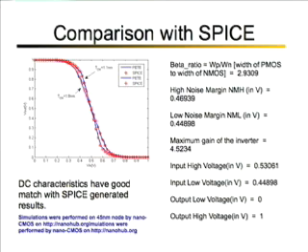And the two different curves here are for two different values of the oxide thickness. One is a thin oxide, which is 1.1 nanometer. The other is a thick oxide, which is 1.8 nanometer. And we can clearly see that as the oxide has been scaled, the gain of the inverter has increased, and it has been captured very well in this simulation environment.